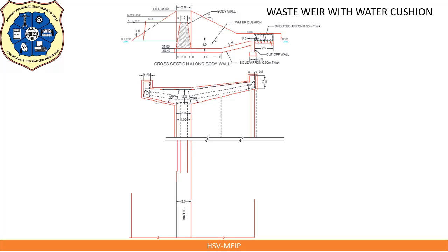Remove projected lines. Again, you have to remove all these projected lines. Now draw splayed wing wall as per the splay 1 in 3 and 1 in 5 upstream side and downstream side respectively. Extend the splay line up to the projected line from bottom view. You will stop the wing wall at the same place where we stopped in the top view, bottom view, sorry.